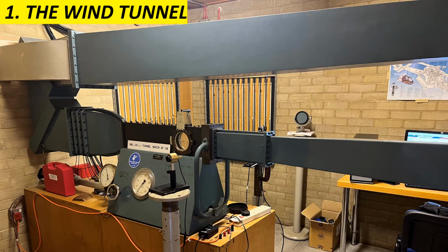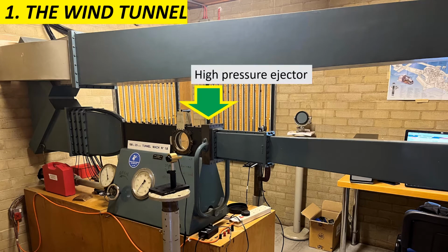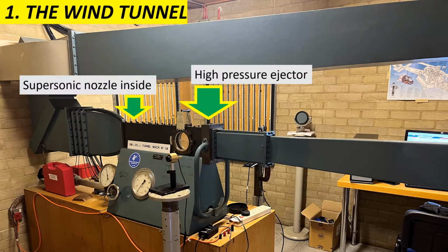Showing here is a supersonic wind tunnel. It's a small one, and I think also it's a historical one. It has been in this laboratory for at least 50 years. It's an induction type wind tunnel. So we have the high pressure ejector in here. You can see the 2 high pressure pipes. They will produce 2 high-speed jets in an ejector.